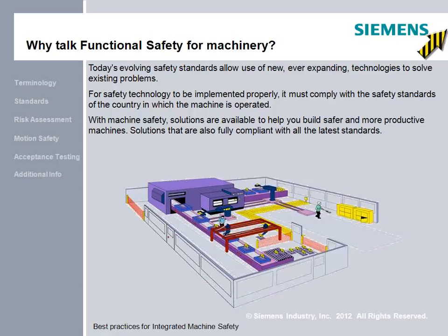So for our purposes today, and to provide a concise definition of machinery, I'm going to fall back to one of the standards, particularly I'm going to paraphrase RIA 1506, the robotic standard. Machinery for our context means an assembly of linked parts, at least one of which moves with actuators, control, and power circuits. We also can consider machinery an assembly of machines. And why is that important? Because a failure or operational fault endangers health, endangers the human, and also, of course, endangers the machine.